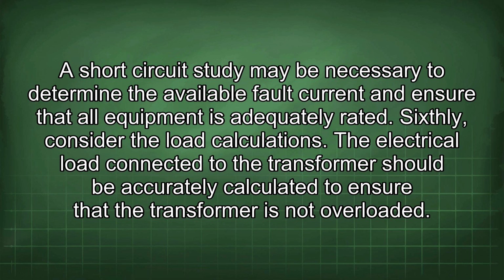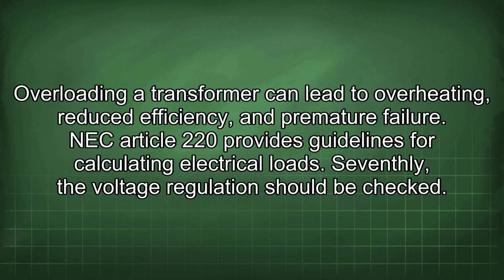Sixthly, consider the load calculations. The electrical load connected to the transformer should be accurately calculated to ensure that the transformer is not overloaded. Overloading of a transformer can lead to overheating, reduced efficiency, and premature failure. NEC Article 220 provides guidelines for calculating electrical loads.